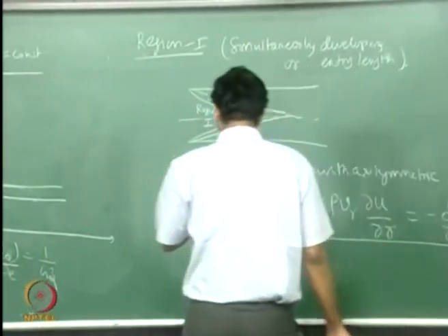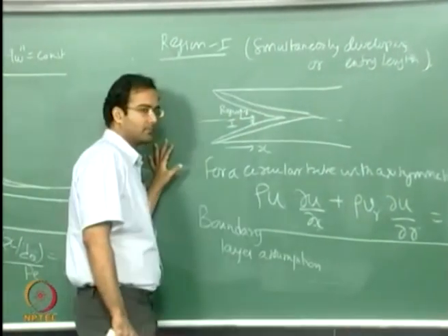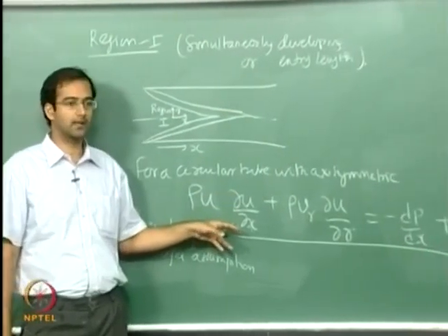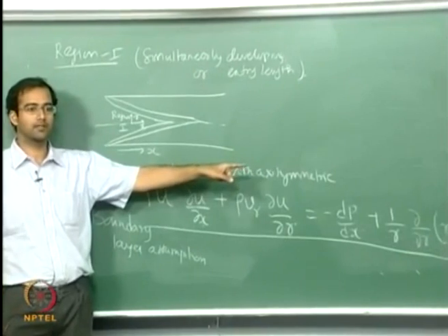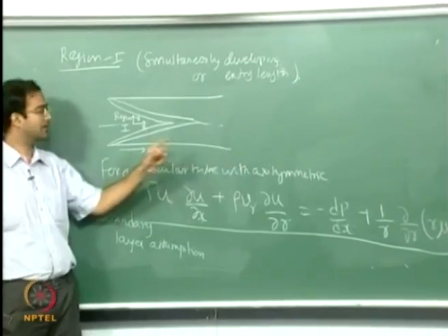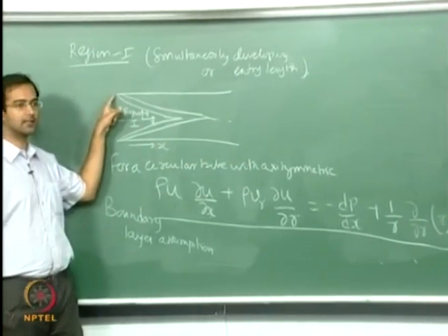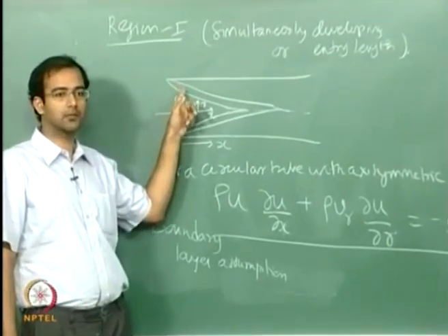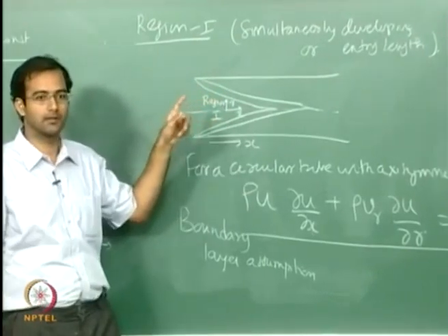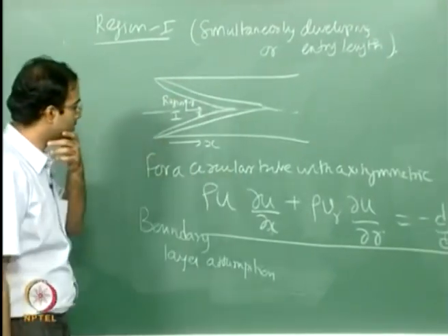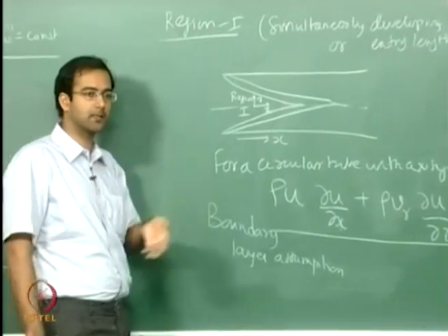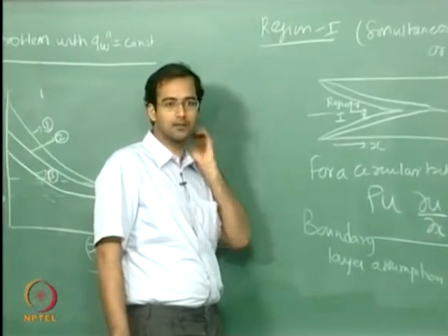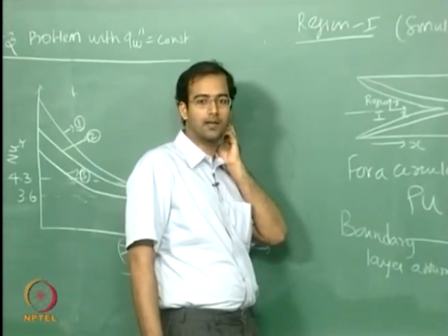So this is an approximation to the actual problem, because what you are doing here, you are neglecting d square u by dx square, okay, so that could be important, because the acceleration in the x direction is important, and also the higher order derivative d square u by dx square becomes important, which you are neglecting here. And also since it is 3 dimensional, you could have 3 dimensional effects if you have a non-circular cross section, okay, so these are also not taken into account.